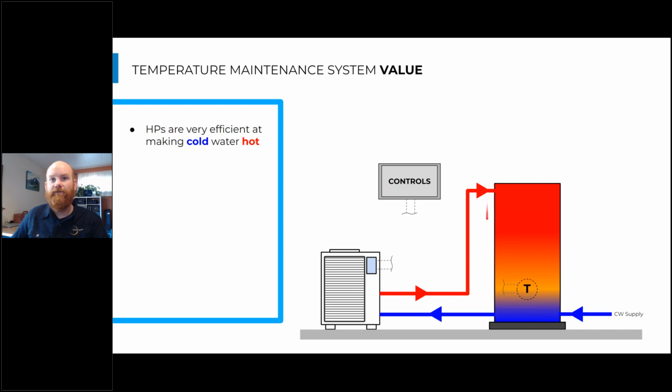And so this makes really good use of our storage tank, as we have a large volume of water that's at or above the usable temperature. And we have a small volume of cool water at the bottom of the tank that we can draw from to add heat to at a very efficient operating point.